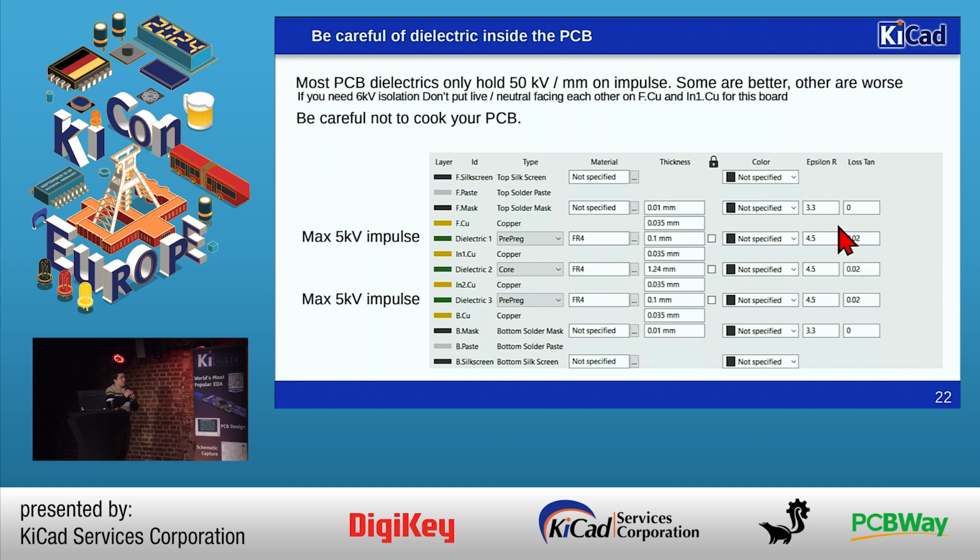One other thing we need to be careful about is that we're always talking about horizontal clearance, but there's also a vertical clearance. Your FR4 cannot withstand tens of kilovolts. Like most common dielectrics, they hold maybe 50 kilovolts per millimeter on impulse, which means that if you exceed this, you will have a conductive path within your PCB.